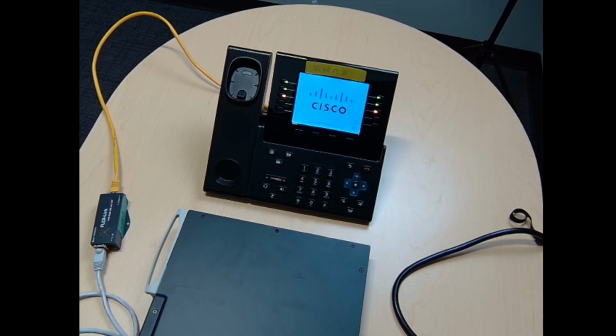Ensure the endpoint powers up by locally powering it and verifying the LEDs light up. If the device does not power up even when locally powered, then the endpoint is faulty. This should be an exhaustive list in diagnosing PoE issues.